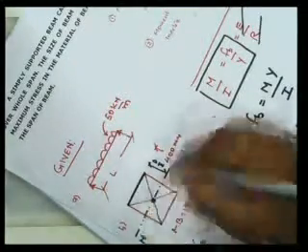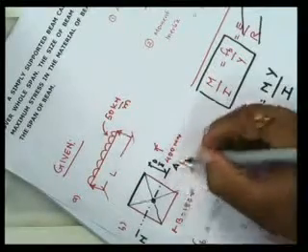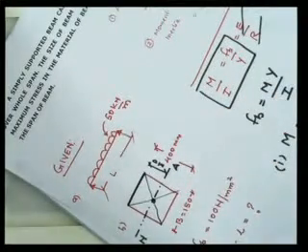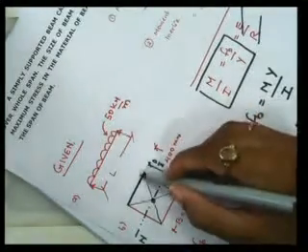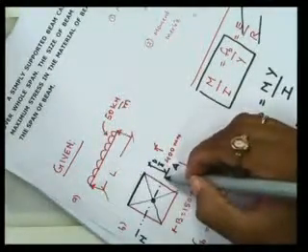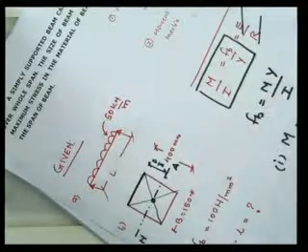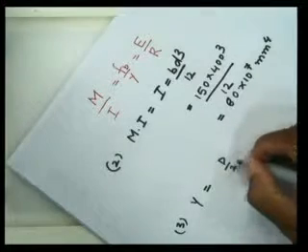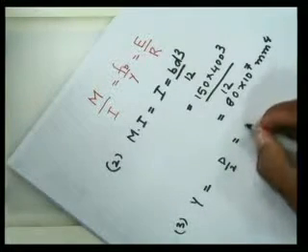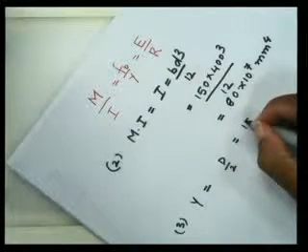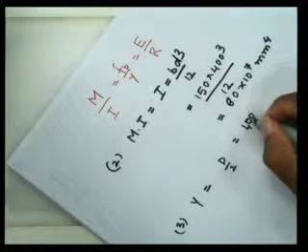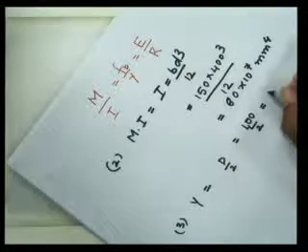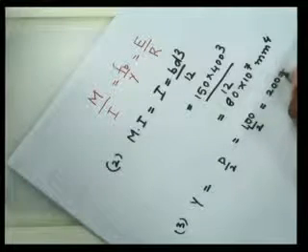The line that passes through the CG is called the neutral axis. So Y is D by 2, that is 400 divided by 2, that is equal to 200 mm.